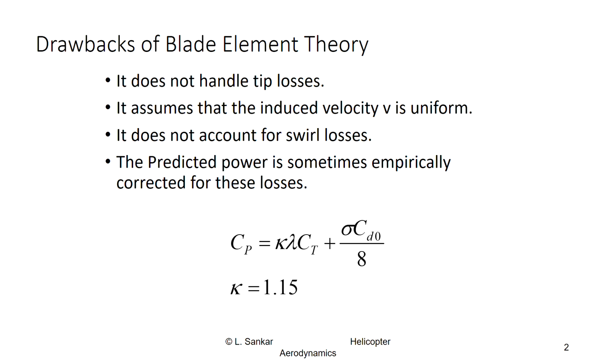So this 15% correction comes from 9% from the induced velocity assumption as uniform inflow. So we are going to try to correct it first, because that's the biggest source of error, that the induced velocity is uniform. So we are going to look for a theory which predicts the induced velocity in a somewhat better fashion. So that's what we're going to do in here.